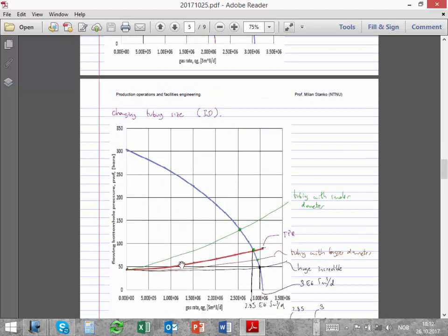And then we say, what happens if we change the tubing size? Okay, and we say, well, this point should be the same because if I'm keeping the wellhead pressure fixed, if there is no flow, doesn't matter if I have a big pipe, small pipe, any pipe, just the hydrostatic column. Okay, if I have no flow, really the pipe size doesn't matter. So all of them depart from the same point, but then if it's more flat, it means the tubing is bigger. If it's more inclined, it means that the tubing is smaller.